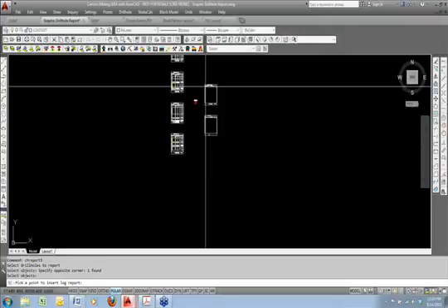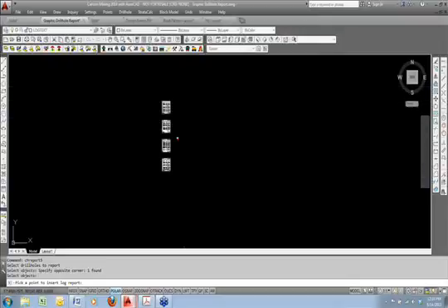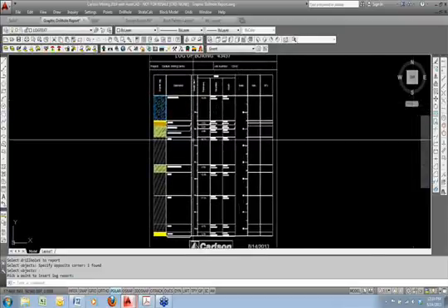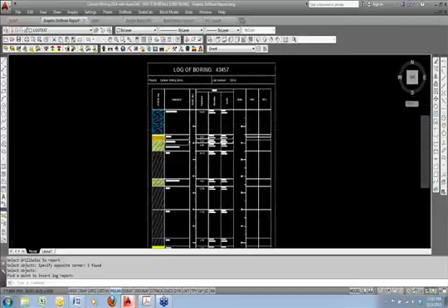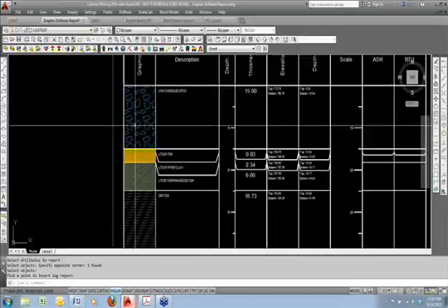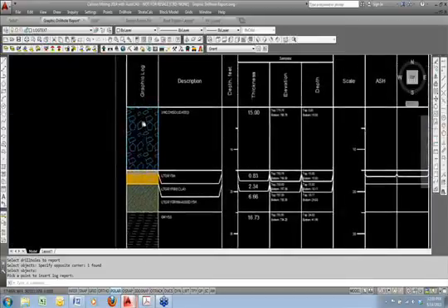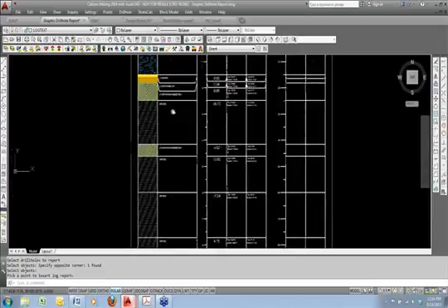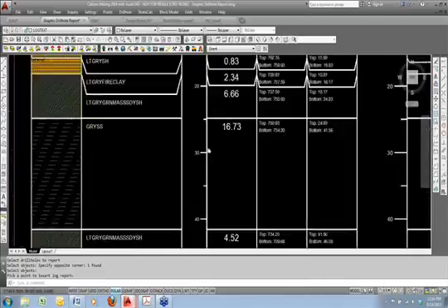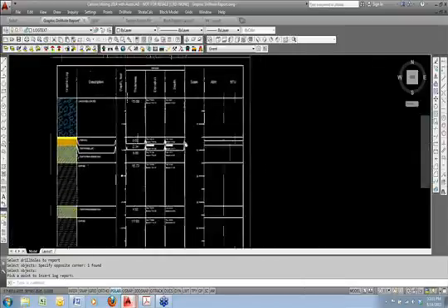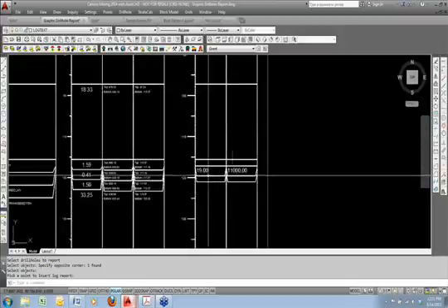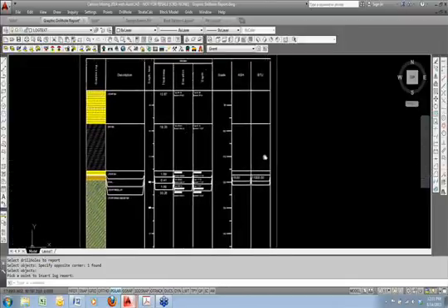Choose OK, and you get a little preview of the size, and you can tell how many pages it will be. I'll drop it into the drawing, and then you can plot this out on a laser printer or a color plotter. Now zooming in, you see the title, and all that text was set in that report window. The one thing we didn't look at was the hatching and the coloring of the different types of strata and seams down below. They're nicely labeled, and depths, thicknesses, and any additional attributes are showing up on the right-hand side. If this was a coal seam, there you see the ASH and BTU values over on the right.